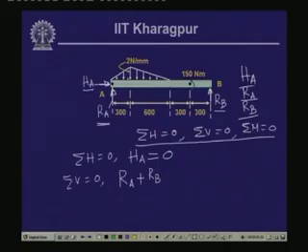Here we have the loads which are triangularly varying. If we look at this particular part, this is 0, this is 2 over a length of 300. So, the load is half into distance 300 times 2 Newton per millimeter. So, this is the load.